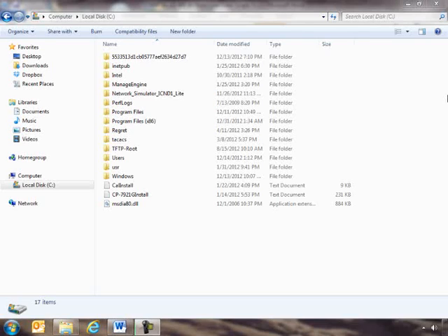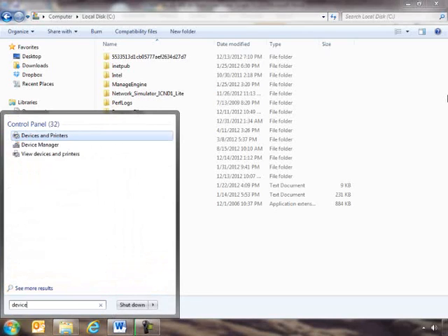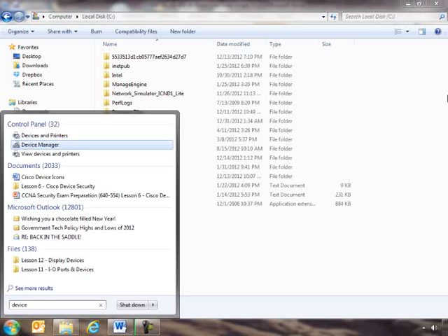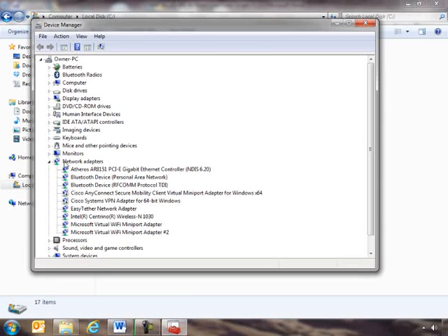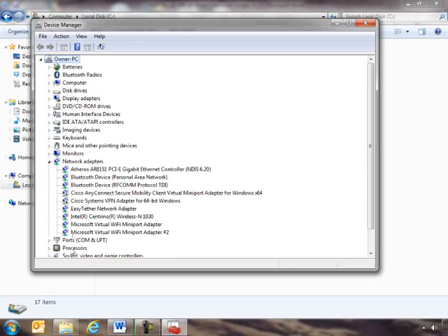Now the one way to know whether or not you have any COM ports actually available and usable is to bring up Device Manager, and I happen to be using Windows 7. Now as you actually look here, you'll notice you don't actually see any COM ports listed. And that's because, remember, this does not physically have any, but you have to use a converter. So I'm actually going to plug in the converter. And now you actually see that COM ports have shown up.